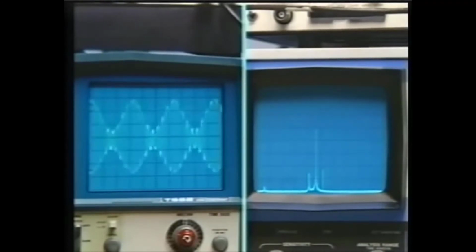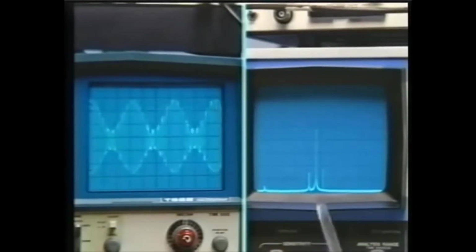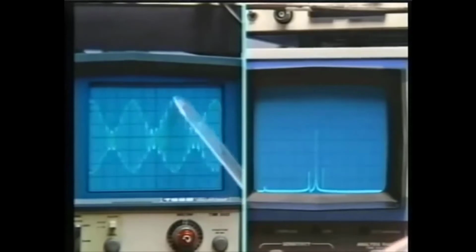And in fact, an envelope detector of the type that we've talked about before is exactly what is used in AM radios because of the fact that it's so inexpensive. And so here the power transmitted required is higher, but the demodulator based on using an envelope detector is considerably simpler.